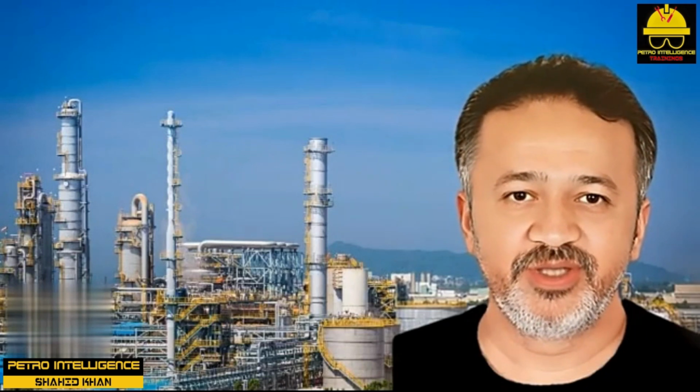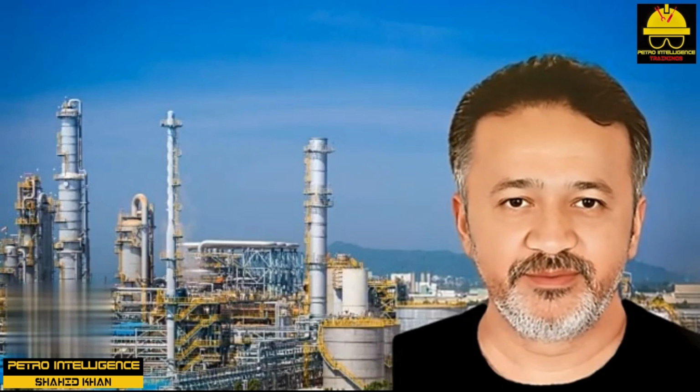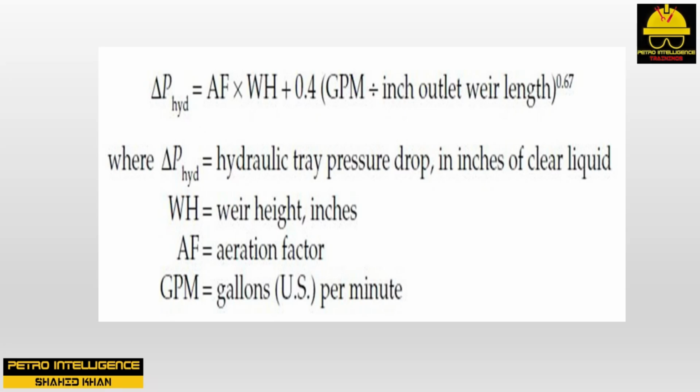The reason is that the fluid overflowing the weir is not clear liquid, but aerated liquid, that is, foam. The fluid on the tray deck, below the top of the weir, is also foam. This reduces the effective weight of the liquid on the tray due to aeration.